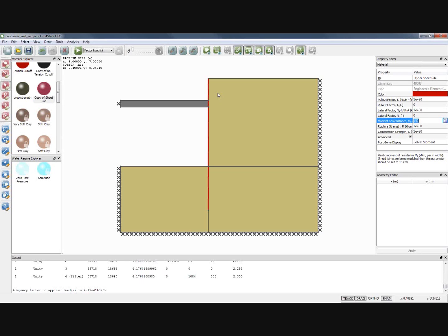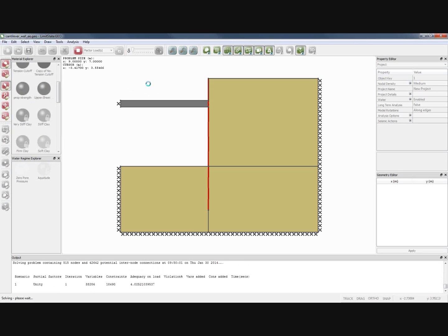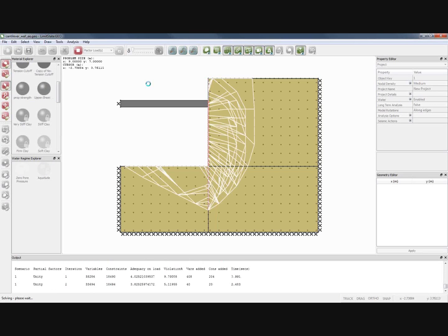1. I can work out quite easily roughly what the bending moment down here would be for that to give me a lateral earth pressure of 1. And actually turns out in this case, because I'm a meter down with a unit weight of 14, it's a half 1 squared times 14, which is 7. If I put that in and then replace that up there, then what will happen is this upper sheet pile will be tied into the lower one, but it will actually happily bend at a stress of 7 kPa. That's larger than would give you active failure, but smaller than passive.